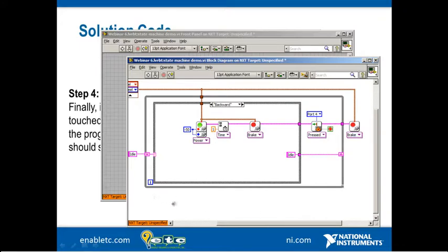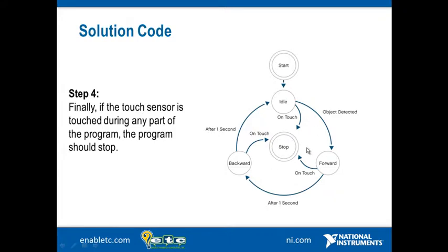So in summary here, without a whole lot of time and a whole lot of effort, and in fact by reusing what is essentially just 2 structures and a shift register, we've programmed up this state diagram. The nice thing about this approach is you can imagine, let's expand this. Let's add 5, 6, 10, 15 states.